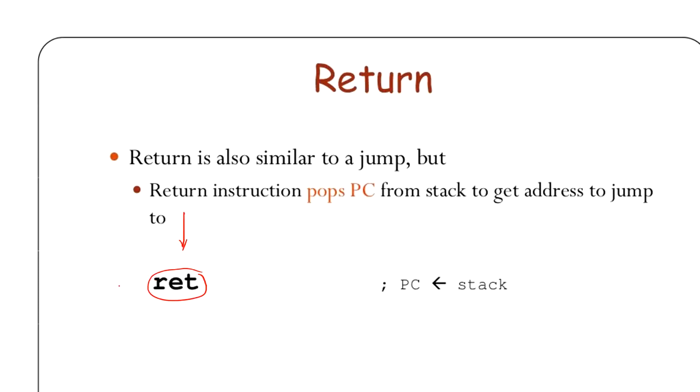Once it is encountered by your program counter, whatever you stored in the stack, like the main program address, that is the program counter address, and whatever your flags, is all restored back to your flag register, and the program counter is restored into your program counter.